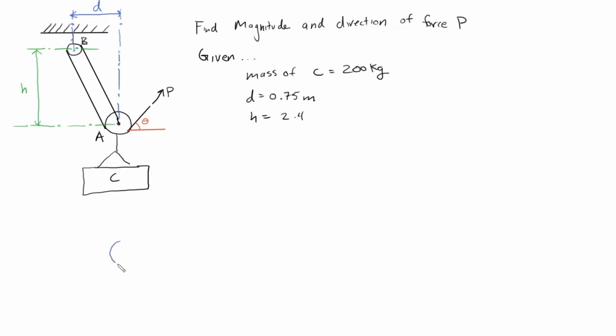We have the pulley itself, and we're going to walk around this pulley and see what interactions occur. One important thing that is stated in this problem is that this is in static equilibrium, meaning that this pulley is not rotating or anything. There's no idea of torque being applied to this pulley. So that's one important thing to note. With that being said, the tension forces on this pulley are equal to the magnitude of this force P.